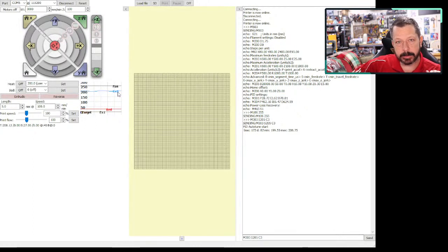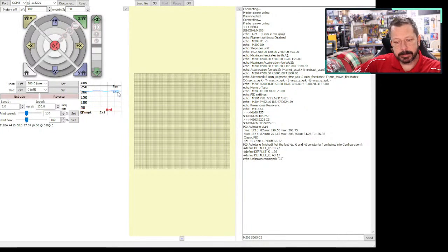Do I turn the heater on full blast? Do I turn it at some partial temperature or energy? Do I vary that? And the algorithm will take these PID constants and be able to better control with less overshoot and undershoot, cycling around your set point type of thing, in your system. And in this case, we're using it for our nozzle heat.